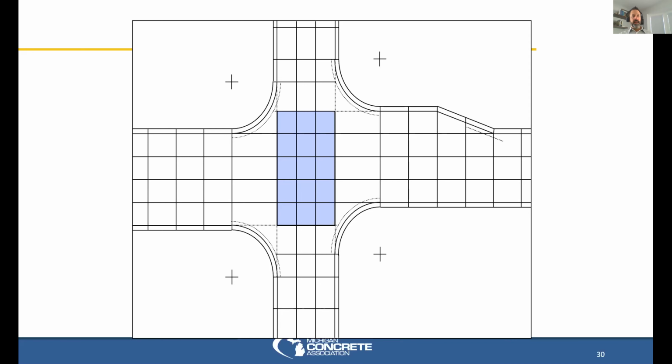And you go through the analysis of the shrinkage that a concrete slab undergoes. The reasons why we put joints in are because of shrinkage, and then the future expansion that it will ever see through its lifetime.